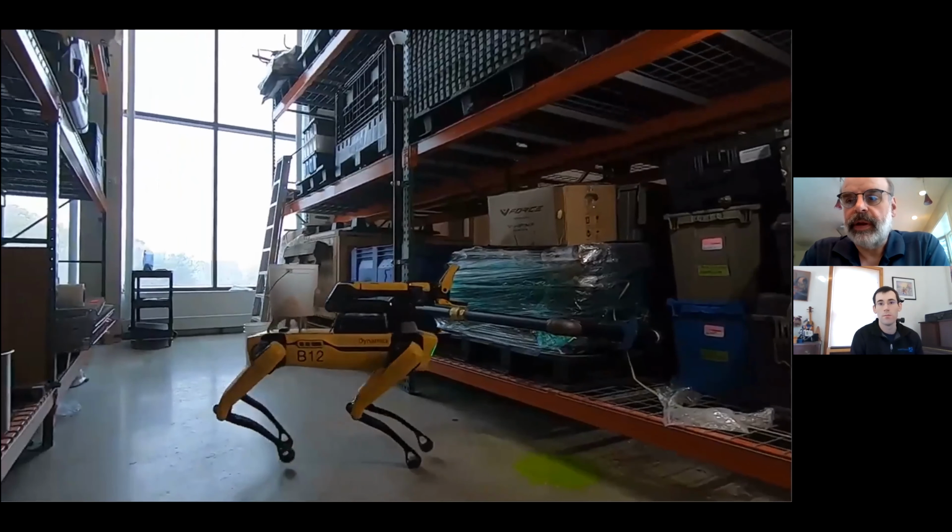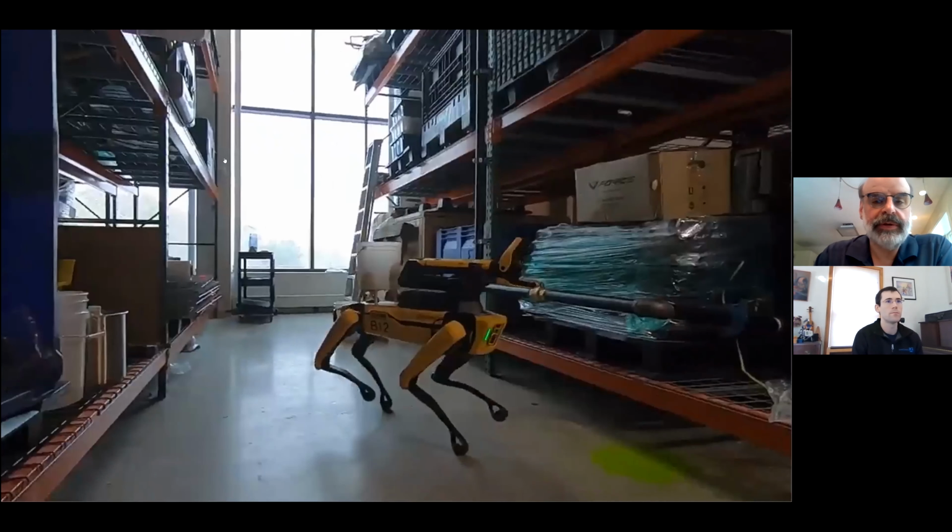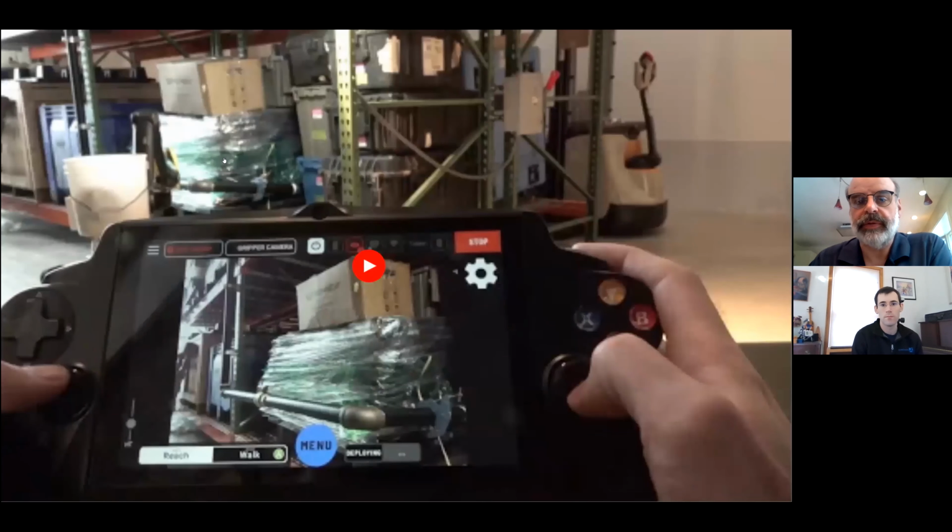It of course depends on your network, if you're on Wi-Fi versus directly wired into the robot. So Andy, if I can cut in on that one for just a second, I think the key issue there is going to be network latency. So it's very much going to depend upon the particular radio environment you're operating in. Our intent is that things like this constrained manipulation mode and these semi-automated grasping features reduce the need for the user to directly control those types of interactions, that you can in fact rely on local control and autonomy on the robot to actually execute that part of a task for you. And so that's how we think we really come at that problem in a way that's a little bit structurally different than what most people are doing with teleoperated robots.